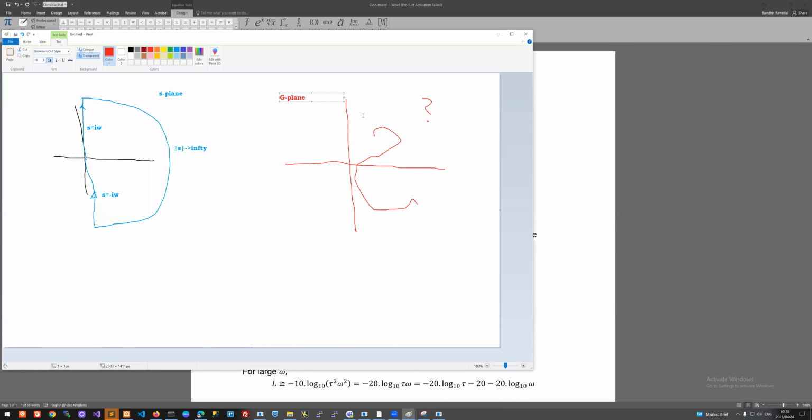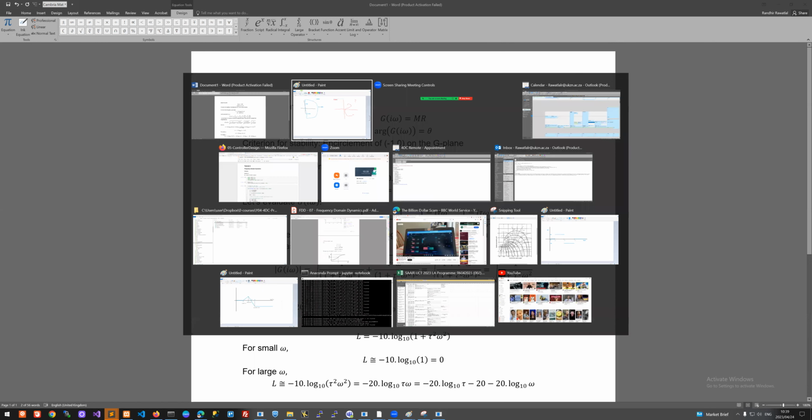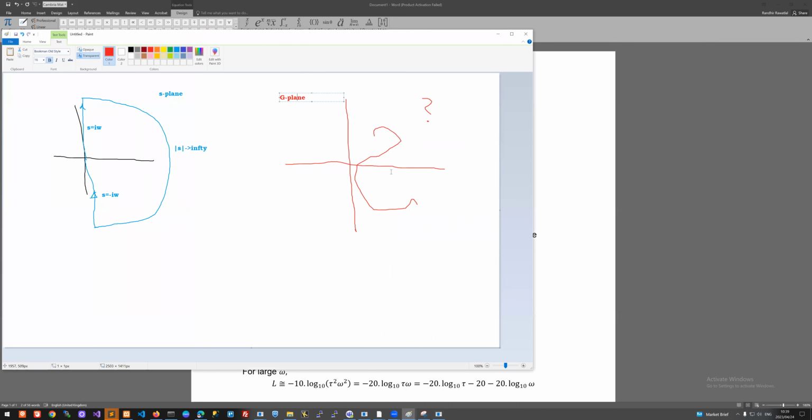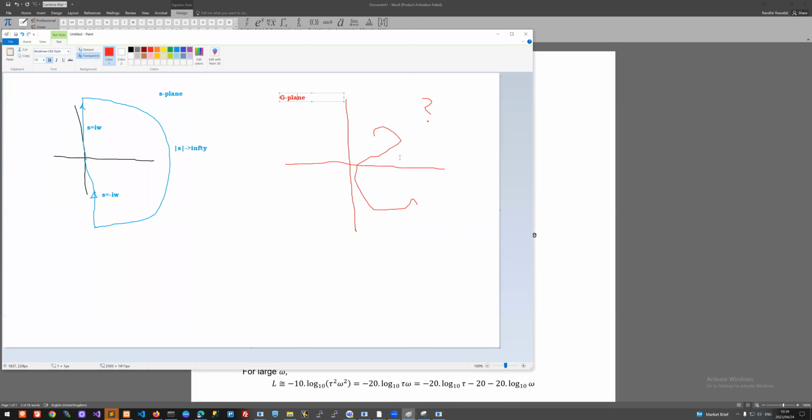But still, it's a question how we'll plot that out. How will we actually use that to develop our controllers? One is, of course, we can just try and plot it here on the complex plane. But the alternate suggestion is that we do it instead using this definition. So yes, we can always plot G like this. When we've got G of I omega and the angle of G of I omega, we can just go ahead and plot it on the complex plane. But it's a bit harder to imagine how to move it around.